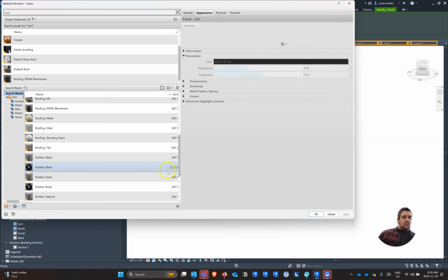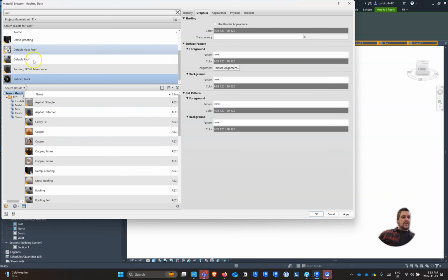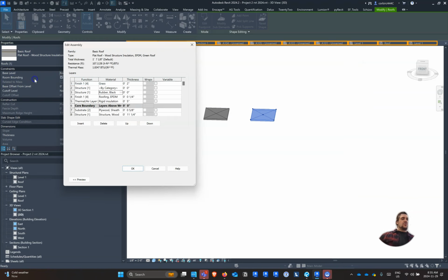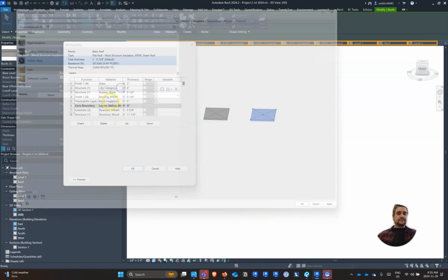It doesn't really matter what we put it under, but I think typically a protection board is some sort of rubber material. So let's put a protection board, and this would just be a 1/2 inch, or actually maybe not a rubber material. This could be a drainage plane actually. So protection board might be under the EPDM, and then this would be like a drainage board. And then on top of here we'd have the earth, and so we'd do maybe 4 inches of earth.